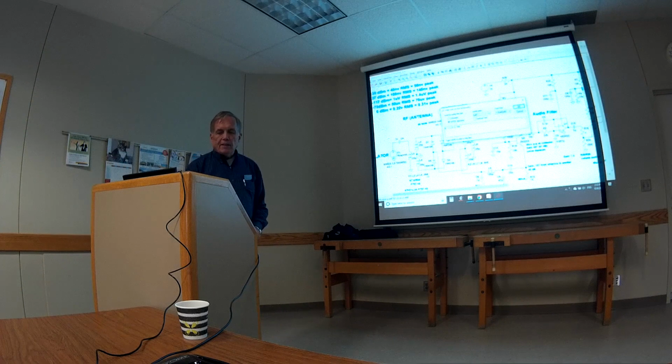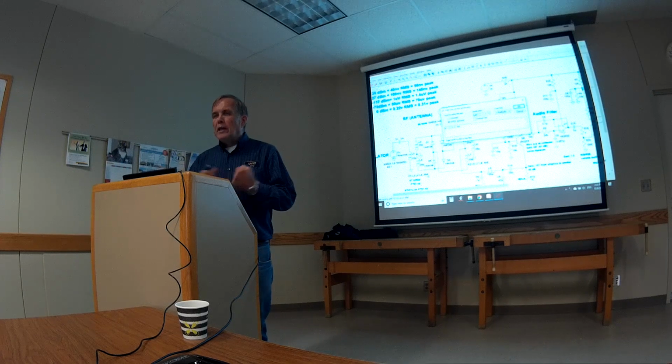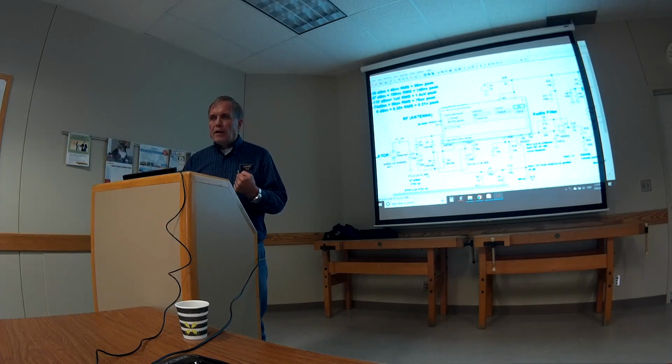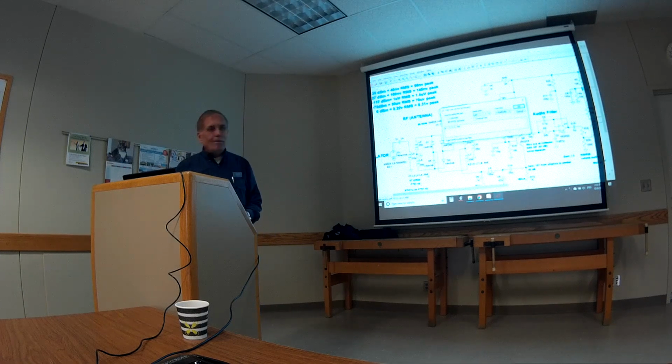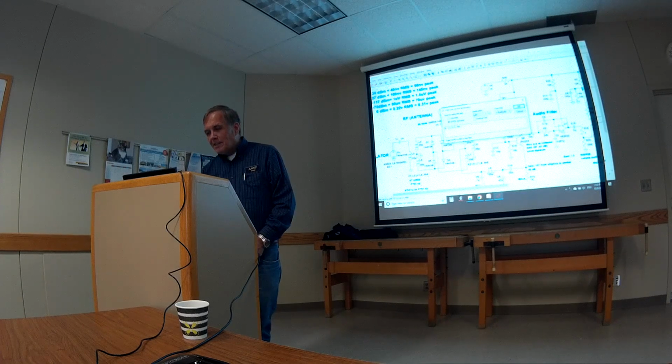So K1 is just saying, for the first coupling, I want to call it K1. Over here, I'll call it K2. And in K1, I'm just going to couple together L3, 4, and 5, whatever you call them. And at 0.999, that's a really tight coupling. You can change the coupling factor to something less, since 1 would be perfect coupling. It's probably not 0.999, but something close to that. So that's just a nice way of modeling: put in 0.999 and see what it says.